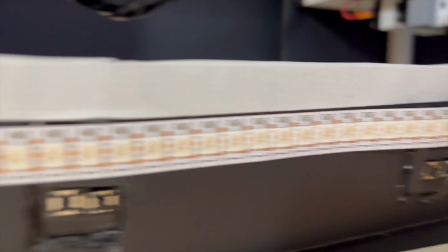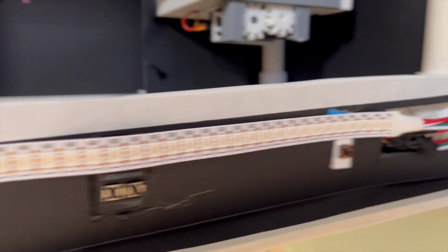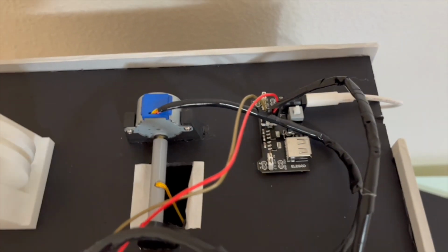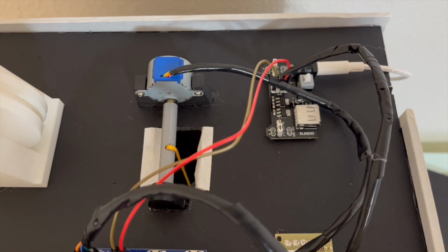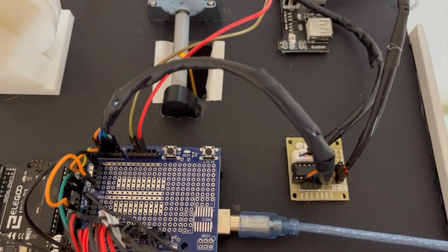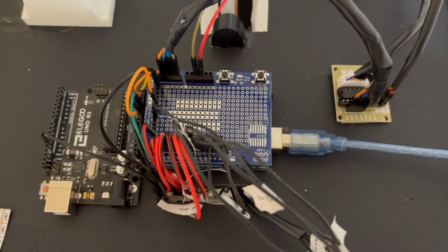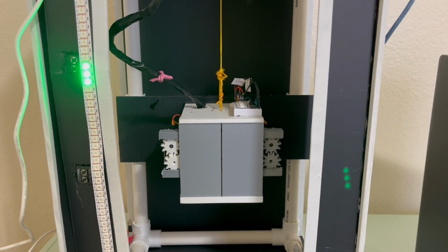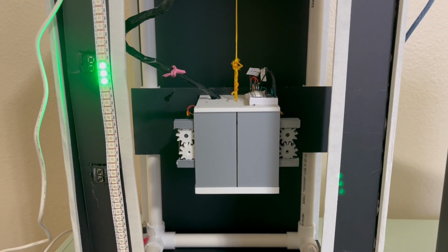The 6 floor buttons and the NeoPixels are also connected to a single ground point and are wired directly to the main Arduino. The servo motors and the secondary Arduino have their own power supply, while the main Arduino is powered directly from the computer. Finally, the elevator's door mechanism represents another crucial component for user interaction and system safety.